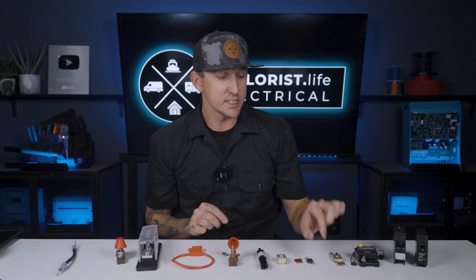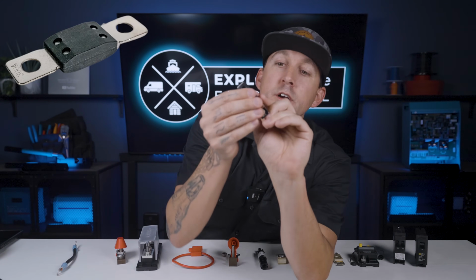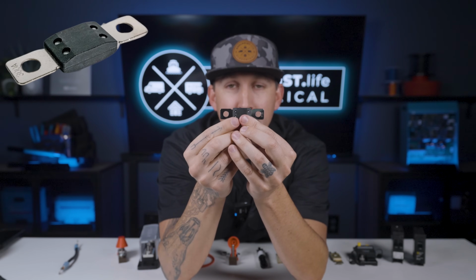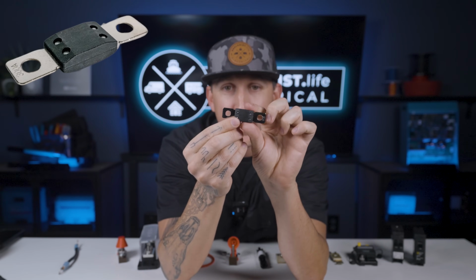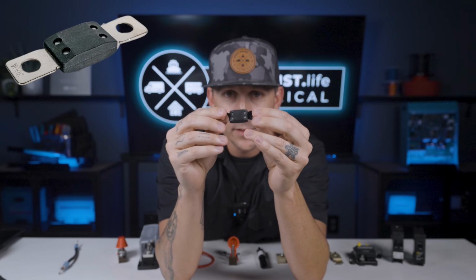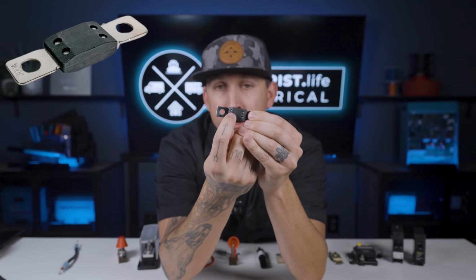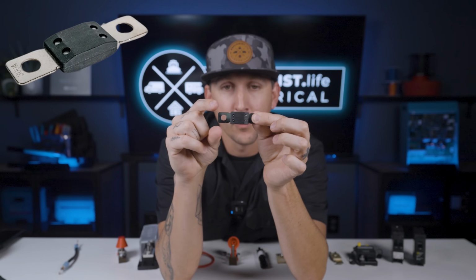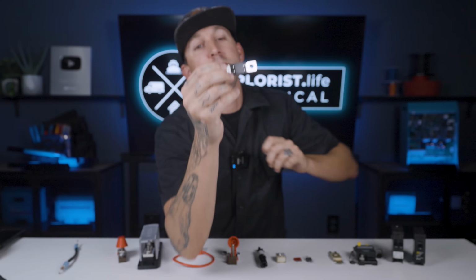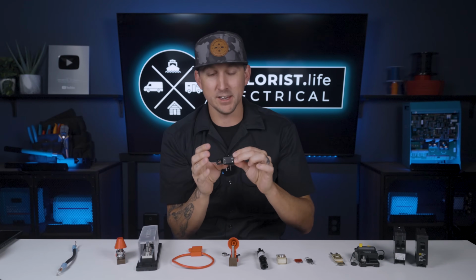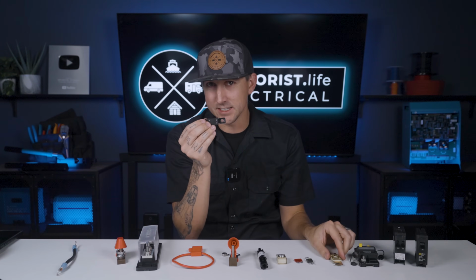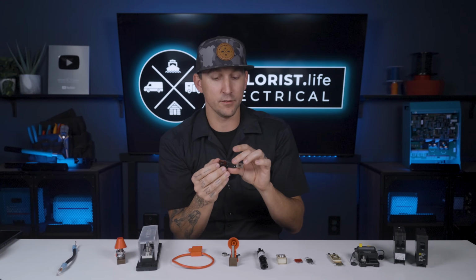The next one is a mega fuse, and it works in largely the same way. Power is coming in one side and out the other side, and there's no window on this one, but there's still a filament on the inside that is going to melt if there's too much power flowing. And I think some people think that there's a downside to not having a window, but it's really easy to test if a fuse is blown.